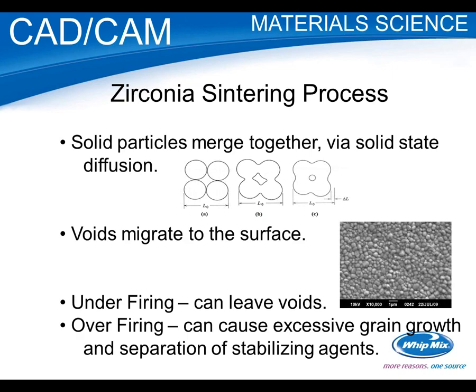A lot of folks think, well, if I overfire, it'll get there. And actually, if you overfire, you'll get this glassy look, and some people may think that means it's more translucent. But if you've gotten that far, you've greatly destabilized your product. It's going to be very sensitive to low temperature degradation. You'll have cut the strength in half. So again, be wary of overfiring.